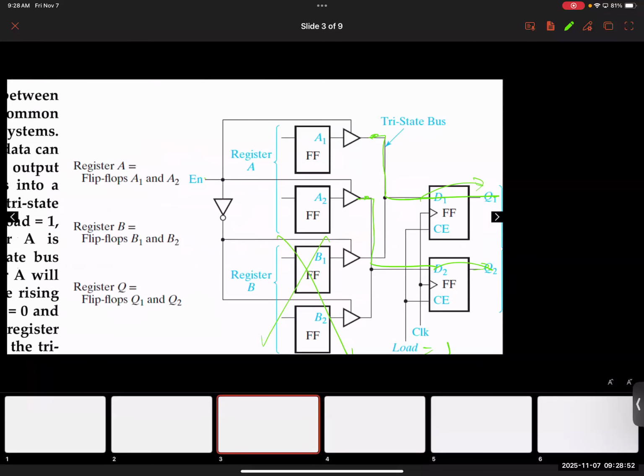But remember, when you're sharing a bus, do you guys remember what a bus is? Typically, imagine if I have 16 flip-flops that are sending 16 bits of information to another flip-flop. I will have to draw 16 lines to connect them. You can see it will quickly get exhausting. 16 is nothing, essentially. 64, 128, 256. How many lines can you draw? You will lose track of all those lines, right? So we don't typically draw them that way. We just draw one line and say that, hey, it is 16. That means it is essentially 16 lines with 16 bits. It is a data bus.